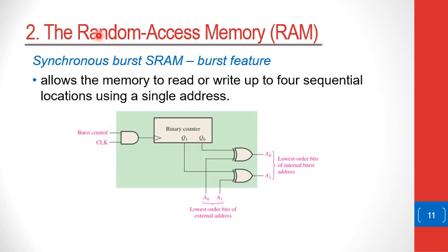And the structure of the burst logic is that it contains the clock and the burst control, and the main feature of the logic is a binary counter, whose outputs are linked to the 2 lowest bits, or the 2 least significant inputs, of the address bus.